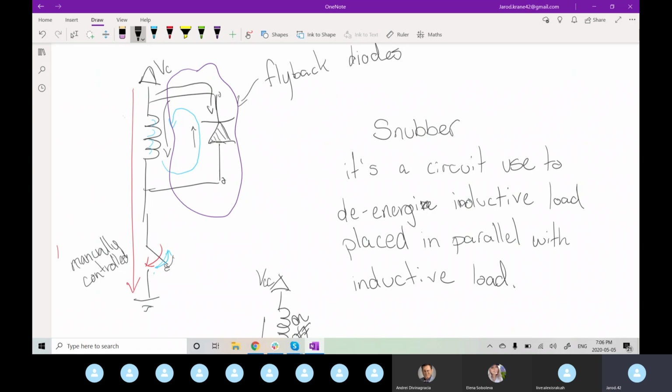In a lot of low voltage applications, or when the switching time isn't too fast or too critical, you'll typically just see a diode. But once you want to start switching faster, you may add a resistor to dissipate the power faster. Okay, makes sense. Thank you.